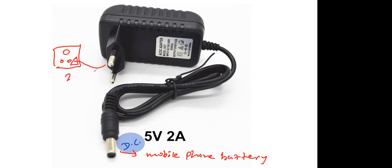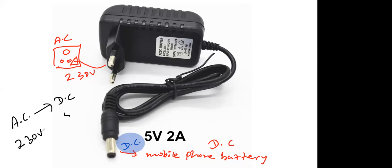This is 230 volt. So again, what is the role here? Again this is called an AC-DC adapter. This mobile phone charger is also called an AC-DC adapter because it converts plug point AC to mobile phone battery DC, and plug point 230 to mobile phone battery 5 volts. So there is voltage reduction and AC to DC. What are the two major functions of this, whether it's a laptop charger or mobile phone charger? Convert AC to DC and reduce the voltage from 230 volts to 5 volts in the case of a mobile phone battery, and around 19.5 in the case of laptops. So that is the role of this box.